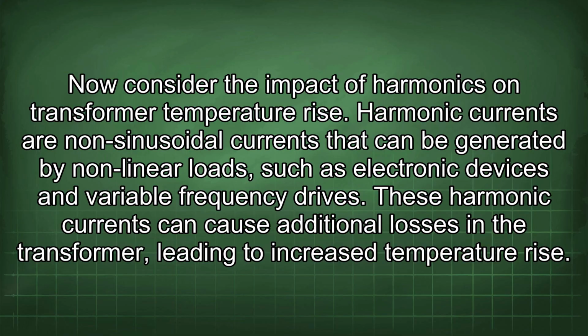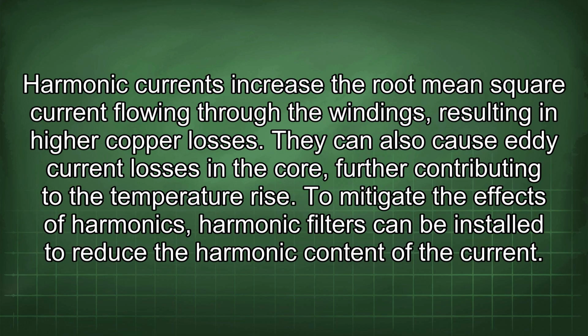Now consider the impact of harmonics on transformer temperature rise. Harmonic currents are non-sinusoidal currents that can be generated by nonlinear loads, such as electronic devices and variable frequency drives. These harmonic currents can cause additional losses in the transformer, leading to increased temperature rise. Harmonic currents increase the root mean square current flowing through the windings, resulting in higher copper losses. They can also cause eddy current losses in the core, further contributing to the temperature rise.